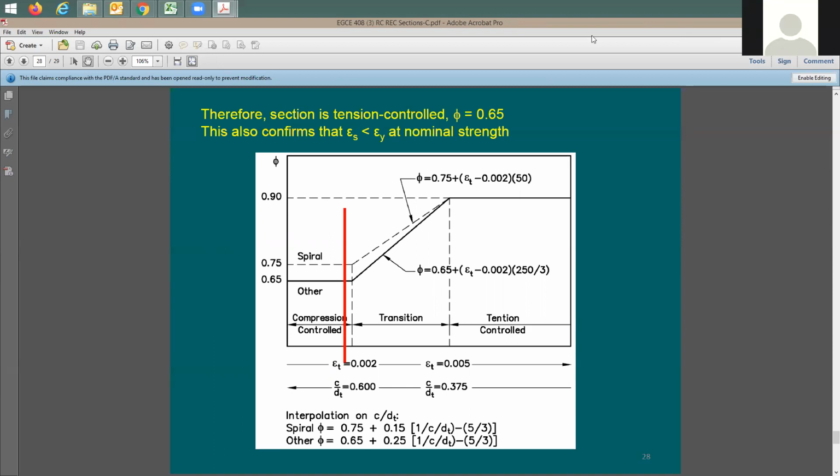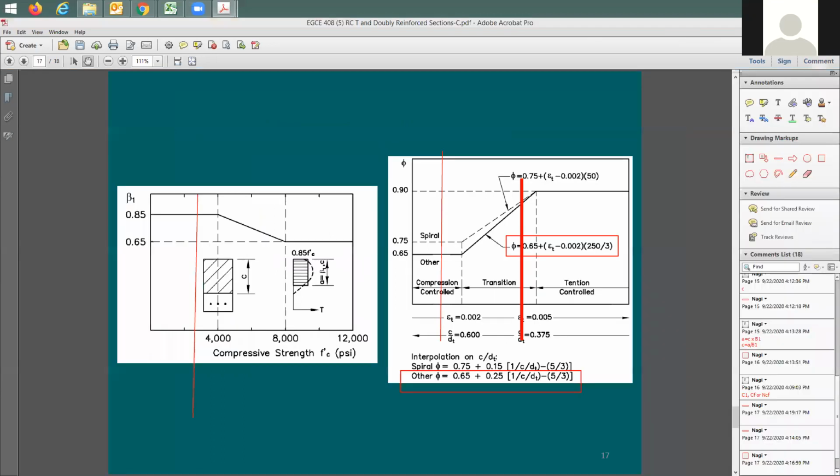Professor, one more question. Yes. For the area of the steel, I was looking up equations because I completely forgot about the steel graph that you gave us. But is it okay to have the formula where I think it's, for example, number 8 steel? I know the diameter is 1 inch, and then we multiply that by pi to get I think the area of steel. That's what I did on the homework.